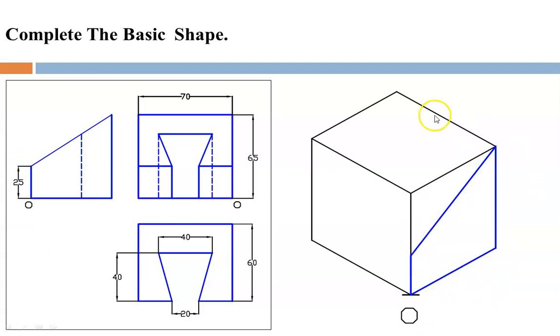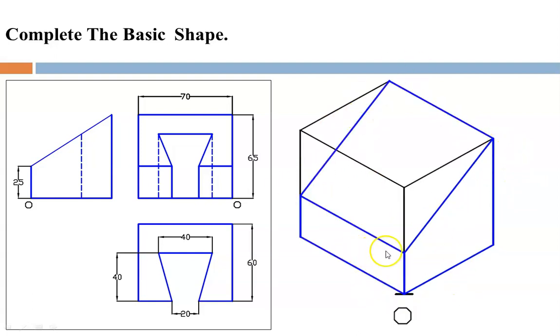So now project this up to the last surface to get the base shape of the object. So here you can see this is the base shape. Here we have projected all the possible points which are visible to you. So this one, then this one and this one, and the same shape is created at the end.